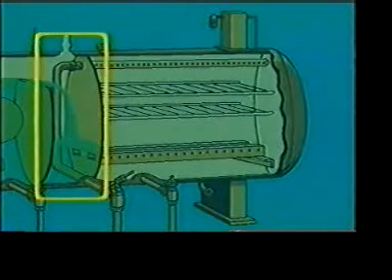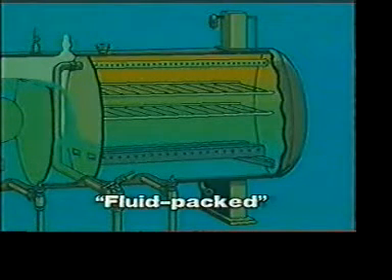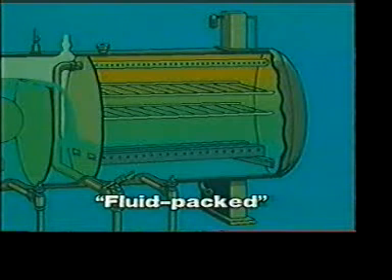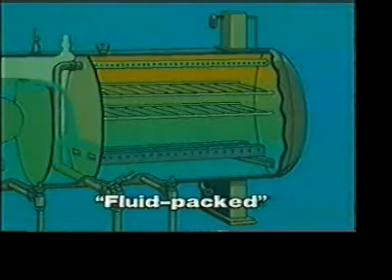From the inlet section, the emulsion flows to the surge section. The major purpose of the surge section is to keep the treating section fluid packed. Fluid packed is a condition where the vessel is completely full of liquid with no gas on top of the liquid.